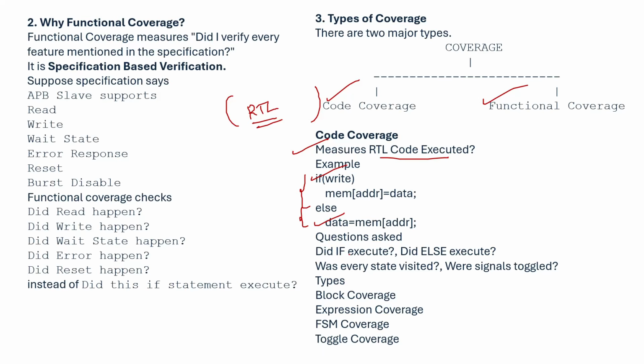Here we need to ask: was the if executed? Was the else executed? Was every state visited or toggled? All these things we verify through code coverage.